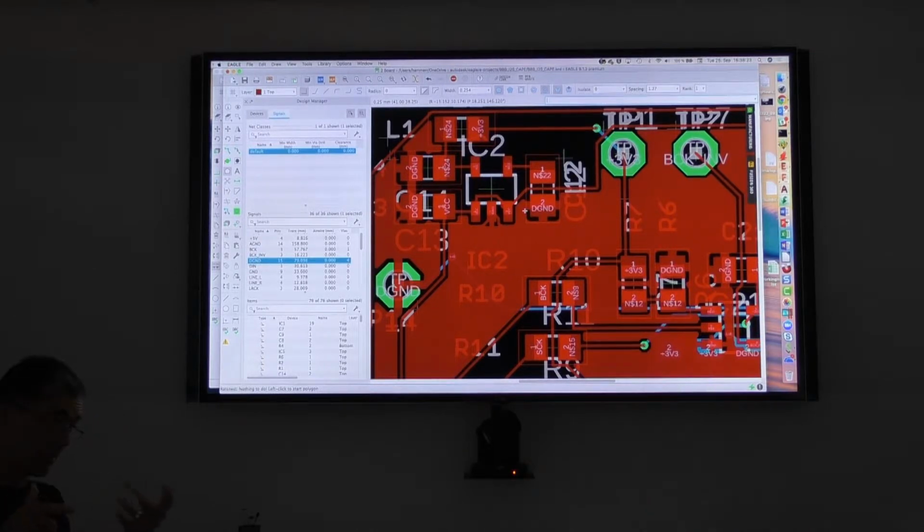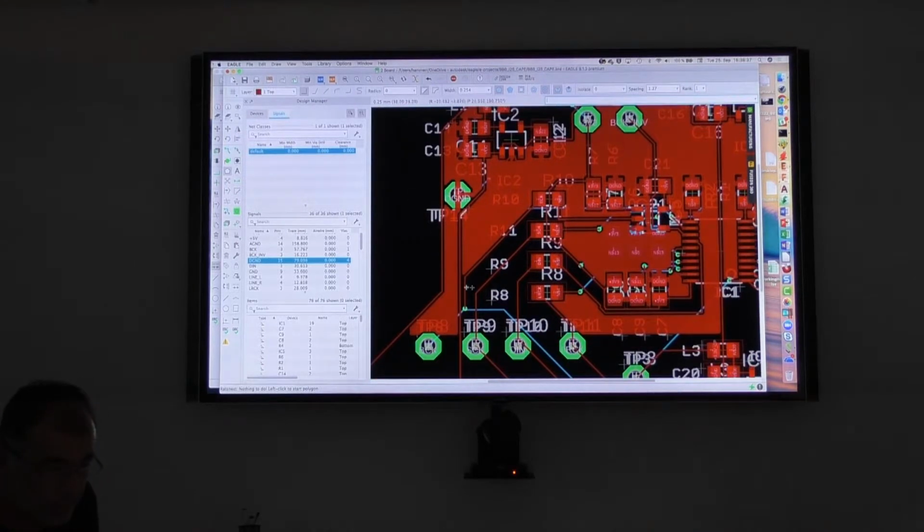My recommendation is to use the same value as you use for your traces, so that it fits. In this area we don't have copper. Why? The whole polygon is connected to the digital ground, and I have no digital ground here, so I don't connect it. I can't fill it.